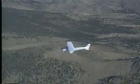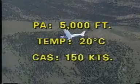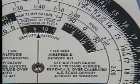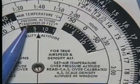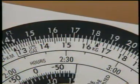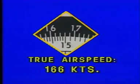As a sample problem, suppose the pressure altitude is 5,000 feet, the temperature is 20 degrees Celsius, and your calibrated airspeed is 150 knots. Using the proper window, align +20 opposite the 5. Notice that the altitude scale is in thousands of feet and plus temperatures are to the left of 0. Next, find the calibrated airspeed of 150 knots on the B scale. Then read the true airspeed of 166 knots on the A scale.